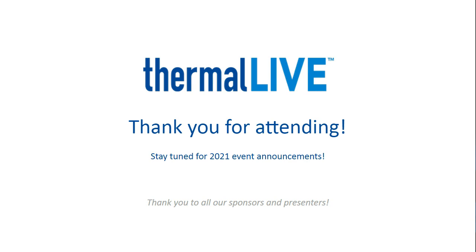Water is a good working fluid. And so that actually fits most practical electronics cooling applications, which is why water is the most universal heat pipe fluid. It's also the best in terms of latent heat and heat transfer capacity. But as you go up in temperature, the thermophysical properties of water start to fall off. And so when you get to those higher temperature ranges, the heat pipe becomes a little less effective, and you may start looking at other solutions in that regime.